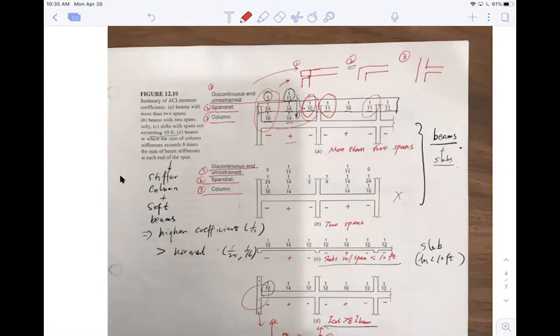So when you calculate the interior support of the end span, which is this span only, negative is 1/10. But you design for the other one, which is also negative, but it's 1/11. You need to do both. And it's going to be symmetric usually. For structural design, it's always symmetric, so the other side will have the same thing.